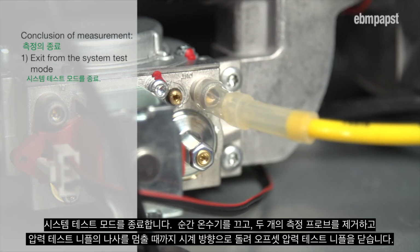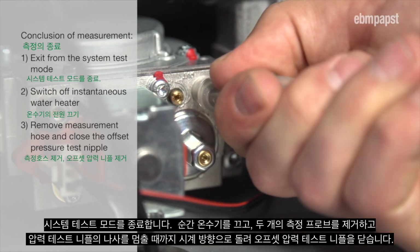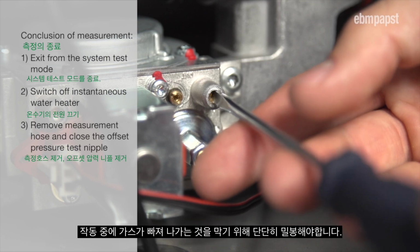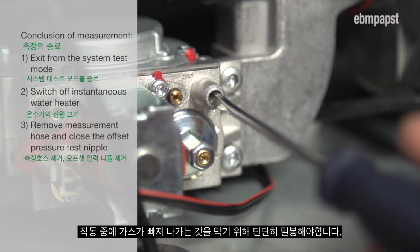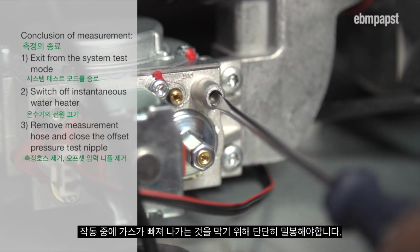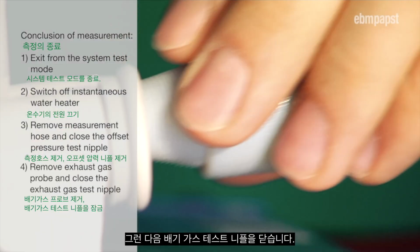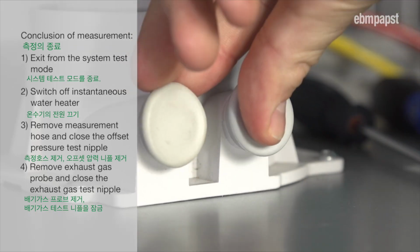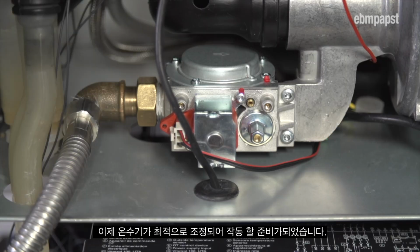Exit from the system test mode, switch off the instantaneous water heater, then remove the two measurement probes and close the offset pressure test nipple by turning the screw in the pressure test nipple clockwise until it stops. This must be tightly sealed to stop gas escaping during operation. Then close off the exhaust gas test nipple. The water heater is now optimally adjusted and ready for operation.